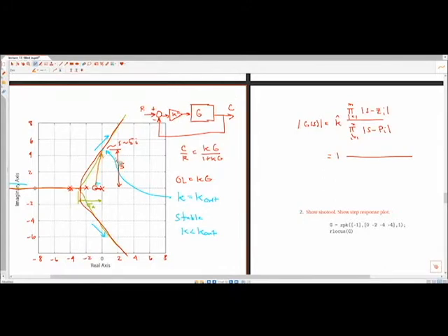All right, so this is the magnitude of this vector going from our 0 location to this point. If we look at this, this is a vector with a real part of 1 and an imaginary part of 5. Via Pythagoras' theorem, we can figure out the length of this vector. In the denominator, we have 4 poles, so we're going to have 4 of these vectors.